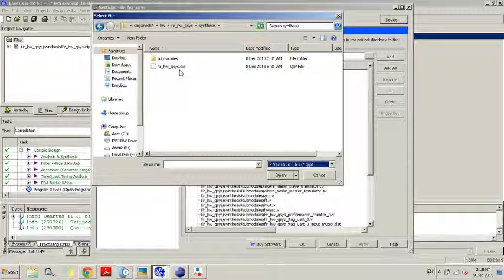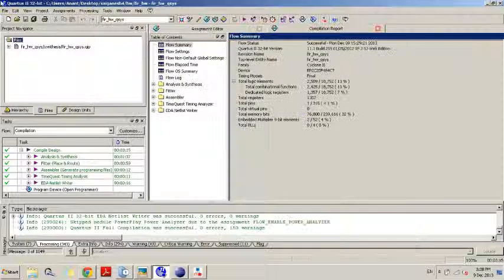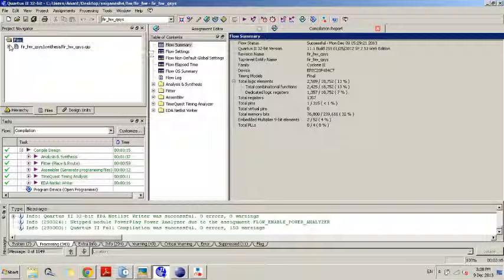This file would appear over here. As you can see when you maximize, all the Verilog files which are required are all added just in the form of one file. Then the second step is to go to Assignments, go to Assignment Editor, and do these two assignments. All the other assignments are not necessary, like the default pin assignments for LEDs and switches, so those are all excluded.